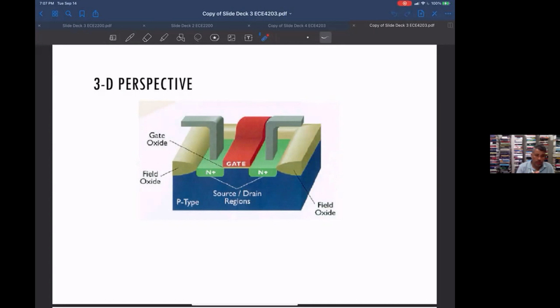Second important concept is that to do that, you are using a lithography process. You have to be able to mask off different parts of the wafer to build the transistors where you want them. All the transistors are sitting next to each other. You can't have transistors sitting on top of each other. It's called a planar process, meaning all the transistors are on the surface of the wafer. Then once you get past the silicon, you start building up layers of metallization with dielectric layers in between.